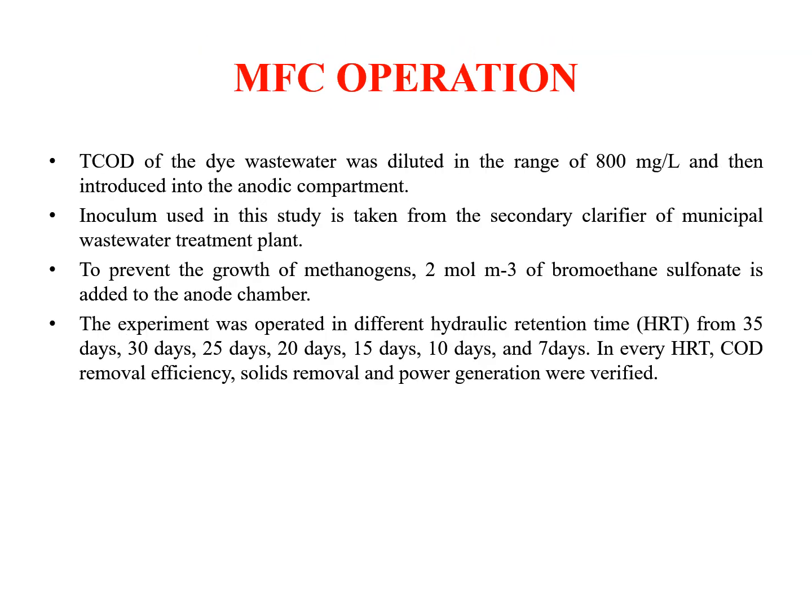MFC operation. Total chemical oxygen demand of dye wastewater was diluted in the range of 800 mg per liter and then introduced into the anodic compartment. Inoculum used in this study is taken from the secondary clarifier of the municipal wastewater treatment plant. To prevent the growth of the methanogens, 2 mol per meter cube of bromoethane sulfonate is added to the